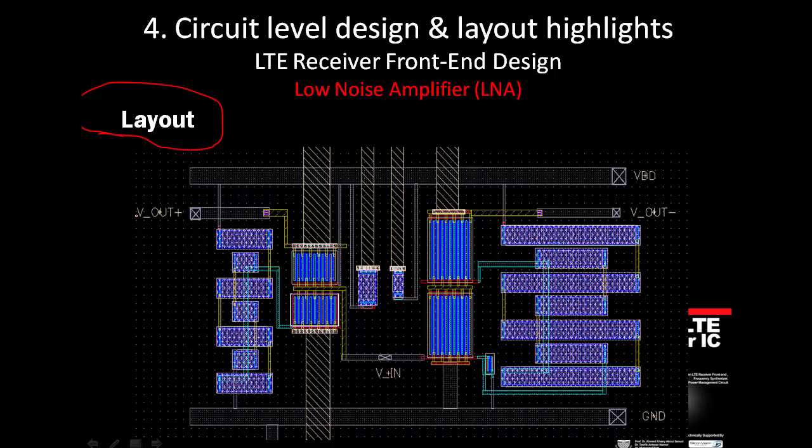And in this layout we draw in a lower level design, we draw our N regions and P regions, we draw our metal contacts, we draw our polysilicon regions, and using the appropriate tool, we make this design and send it to the manufacturer.